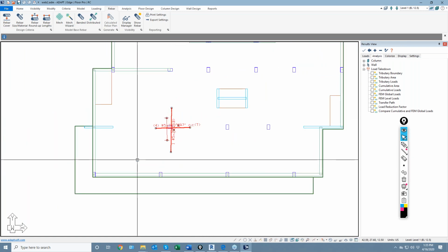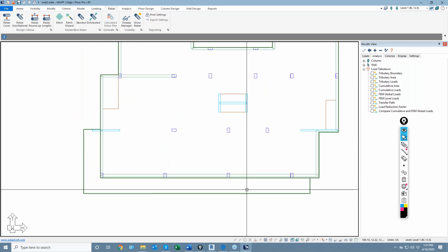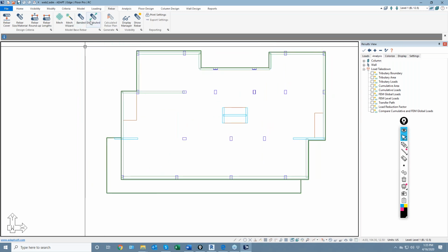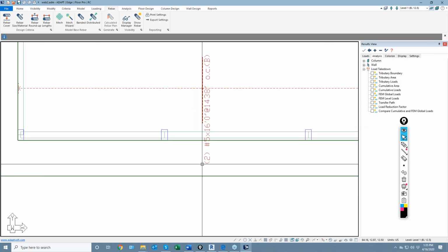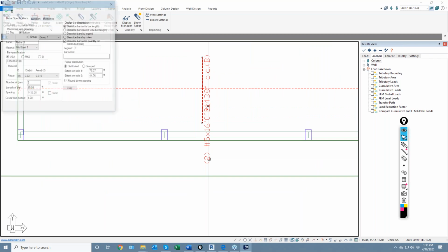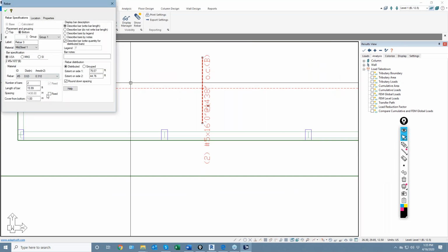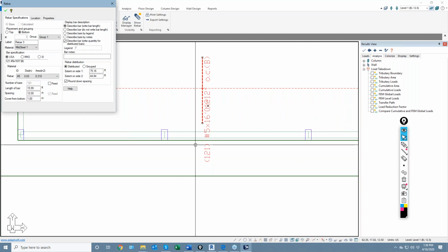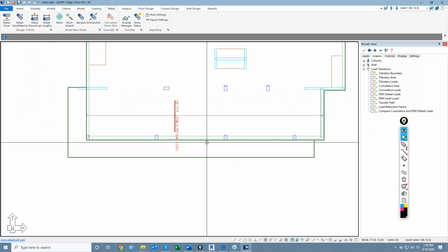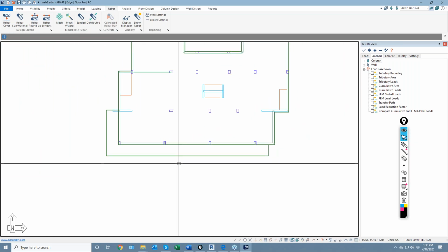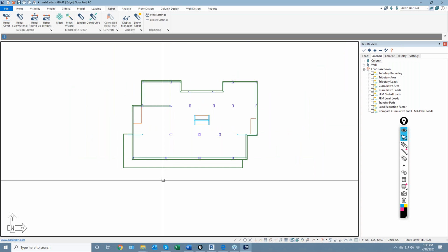This is all generally classified as user defined or base reinforcement. And then distributed reinforcement, we would go ahead and define the bar and then the range. So from point A over to point B. By default, we only show 2 bars in that range. We could change that. Maybe I say, well, I want the spacing to be fixed at 12 inches. Calculate the number of bars, and it calculates 121 bars in that zone from point A to point B. So that's how the base reinforcement is considered.